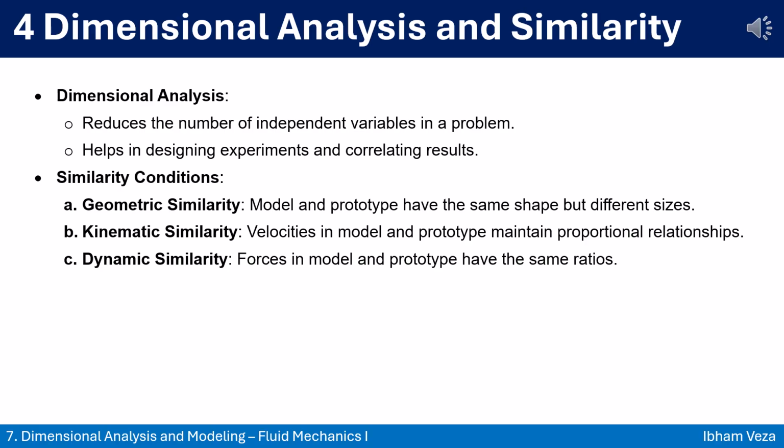Through similarity conditions. A. Geometric similarity. Keep the shape the same, just scale the size. B. Kinematic similarity. Ensure velocity patterns match between model and prototype. C. Dynamic similarity. Balance the forces so the ratio stays the same. Master these concepts and you'll be able to predict real-world performance using small-scale experiments.